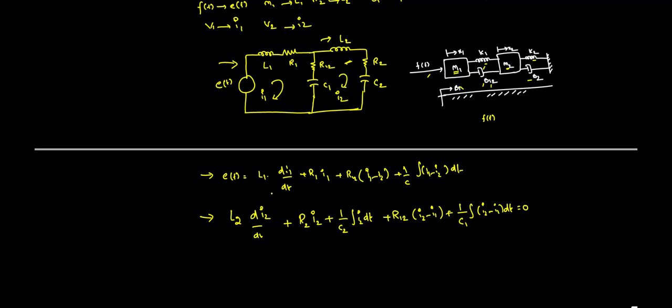Similarly, if you want to write the force current analogous system, you should know the parameters. What are the parameters? Here the force is equivalent to the current, f of t is equal to I of t. Wherever M1 was replaced by L1, now M1 is replaced by C1, and B1, which at that time was a resistance, will now be an admittance.